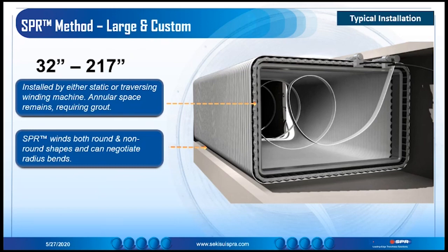Due to the custom nature of the host pipes rehabilitated by the SPR product, there are two different types of products that can be used. The first is what we consider to be straight profile. The second is a flexible profile. These profiles make it possible to mechanically wind not only straight sections of pipe, but also many of the large sweeping radius bends and siphons that make up many of the pipeline systems that are being rehabilitated.